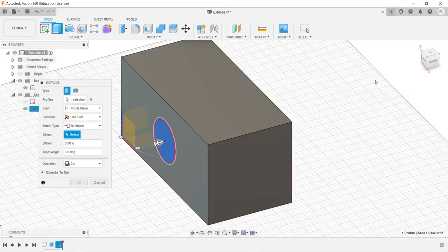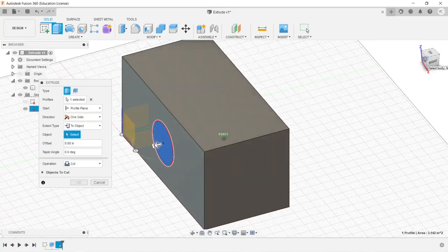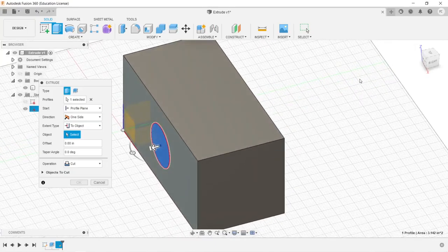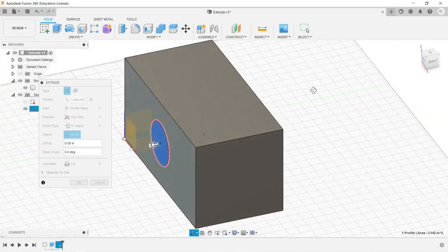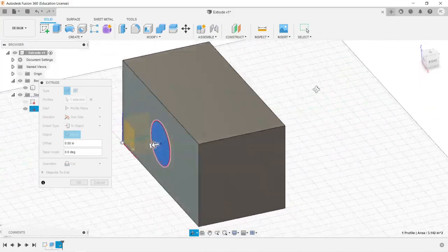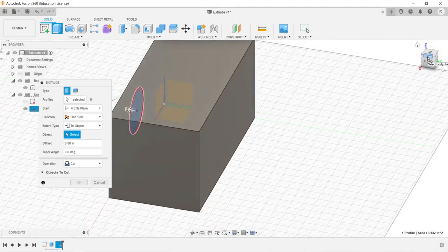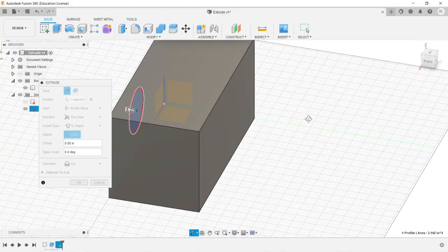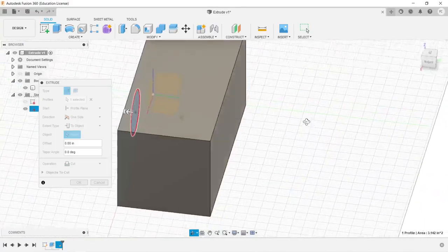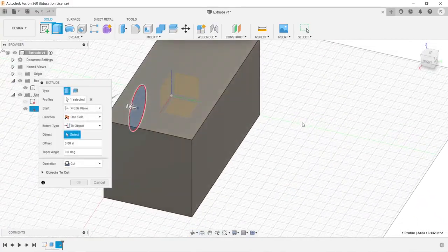Okay, the other way to do this, sorry, I was figuring it out there for a second. You can left click and drag the cube. If the cube is problematic for you, you can also hold shift and use your mouse wheel button or your middle click button, and it will do the same thing. Those are two ways to rotate it, and you do need to rotate things. So you need to either click and drag the cube to spin things around, or hold down the shift key and click the wheel button on a regular mouse to spin around.